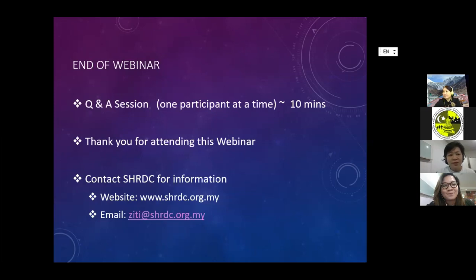Okay. All right. And he has a related question. He's asking if the land pattern, bracket, solder mask, from the datasheet is used to create the PCB footprint. Yes. If you use level A, B, C, they will actually provide you the dimensions for level A, B, C, with recommendations for the opening of the solder mask. But some of our customers prefer that the assembler determine the opening of the solder mask.